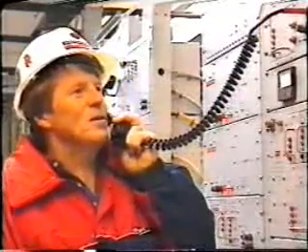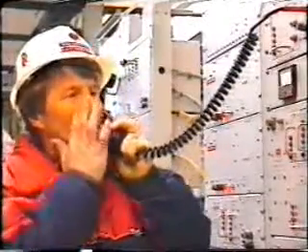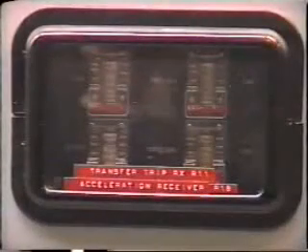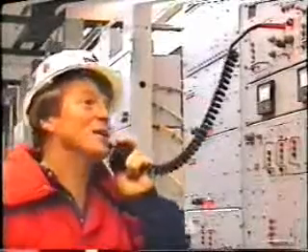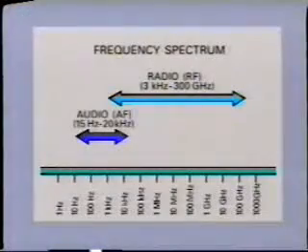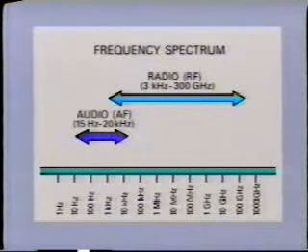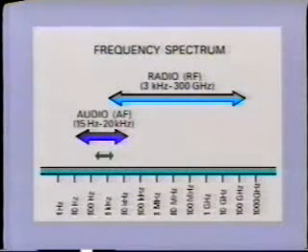Many carriers include facilities for transmitting voice and other audio signals from end to end over the carrier system. The audio signal may be transmitted during the off period of an on-off system, or even across the guard signal on an FSK system. However, the transmission for protective relaying will always have priority and will disconnect the audio transmission when relay operation is triggered. Signals such as voice and telemetry all operate within the audio frequency band, usually between 300 hertz to 3,000 hertz, or 0.3 to 3 kilohertz, in relation to the carrier signal.